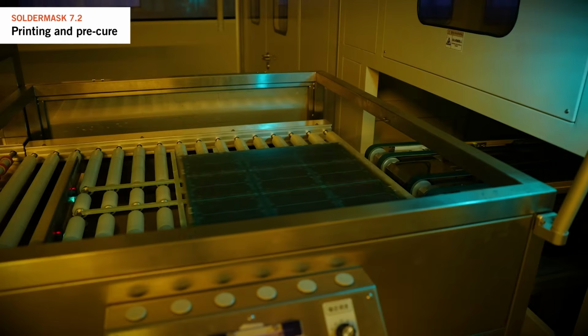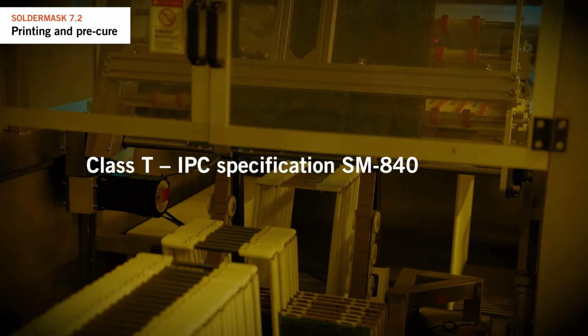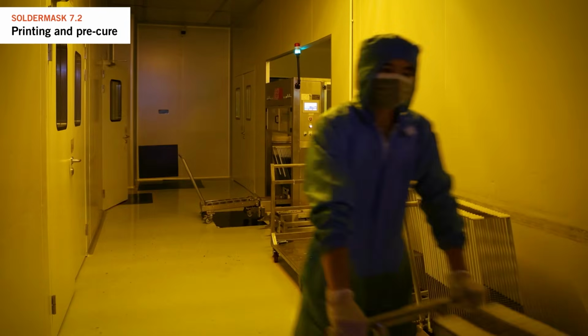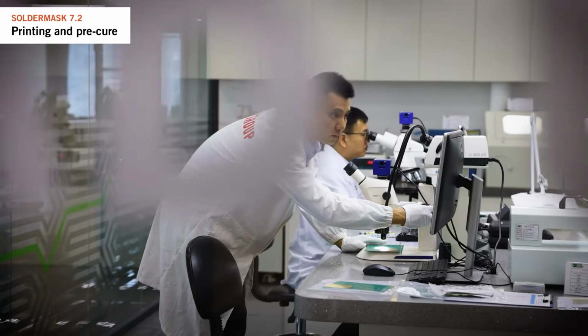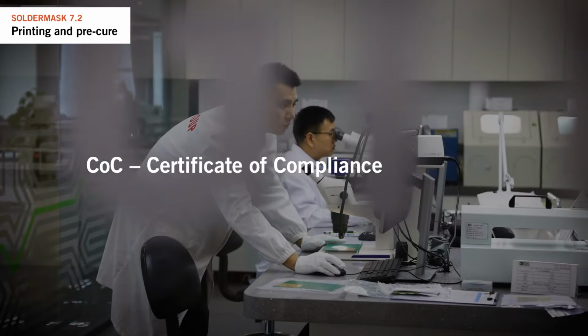We check and approve the solder mask inks used by the factory, ensuring they comply with Class T of the IPC specification SM840. In line with our own demands, we specify the thickness range of the solder mask needed on the PCB, not just on the surface but also on the knee of the track. This ensures a reliable coverage of ink. All these aspects are thoroughly checked and reported in the NCAB C of C.